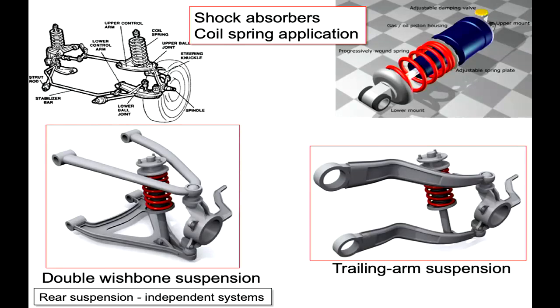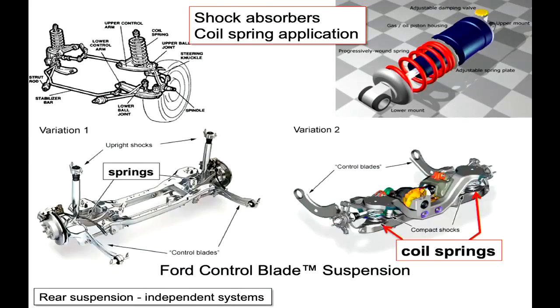And I am aware that it doesn't have to be a coil spring. In Formula type racing, I know that people have played around with essentially a pressurised vessel, like a hydraulic ram, that will do all the spring effect. I don't know how well it's worked, but automotive tends to be coil springs because they're common as muck, reliability is good, and nothing better really has come up, despite all these different variations.